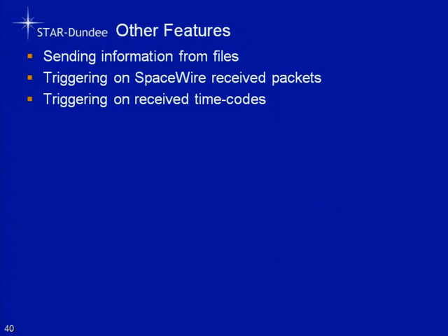They can be external triggers. So we have 4 triggers that can be bidirectional triggers. So you can have up to 4 hardware triggers going in, and use those to trigger events. We've also got some pattern matchers. Because one of the things you might want to do is, say, have your camera, and because it's got a SpaceWire interface, you're going to use something like SpaceWire RMAP to control this camera. So you're going to send an RMAP command to the camera to turn it on.